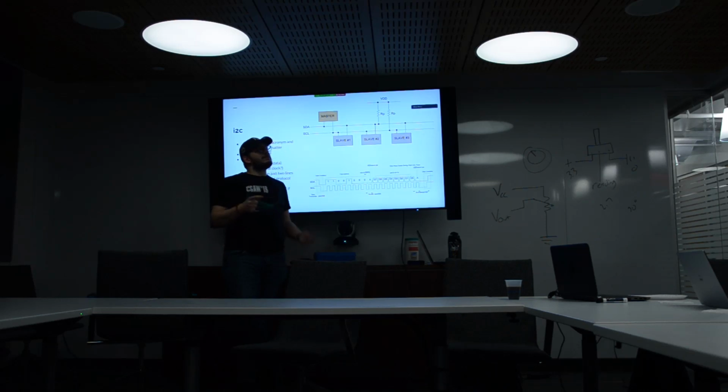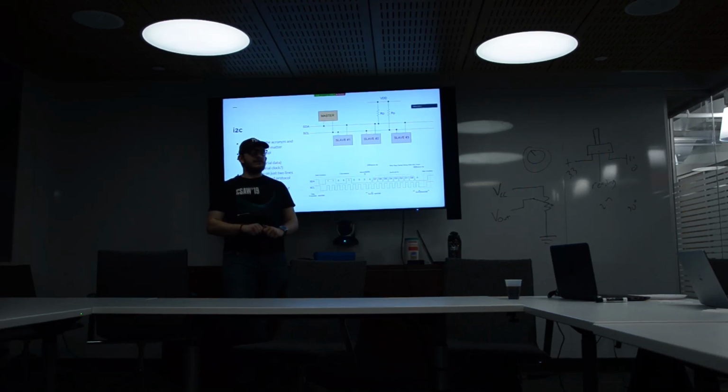In I2C, the clock is handed over. So it's understood that after 8 or so clock pulses, it is now the responsibility of the slave to drive the clock for 1 cycle, and then it's the master's again, and then it's the slave's again, and then it's the master's again. So that's inherent to the protocol, who handles the clock. SPI again is really, really simple for that because the master's always got the clock. I would argue that on some devices you could even do a clock just in hardware with an oscillator, because it's always driven by the master.